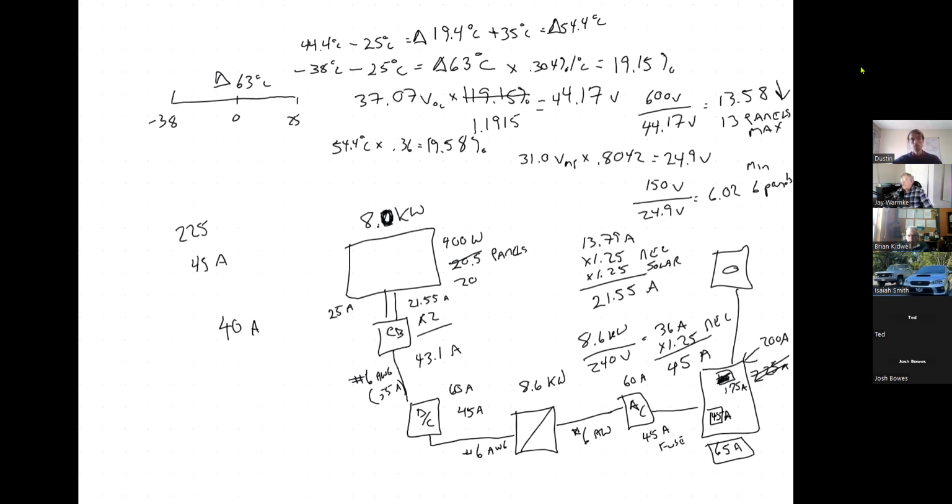So you're going to have to contact your utility or have an electrician come in and make that change. Whereas if you're under the limit, you can just turn off the breaker, put your connection in, and then just turn the breaker back on and everything's fine. So this is a more expensive process because you've got to disconnect from the utility to do it safely.